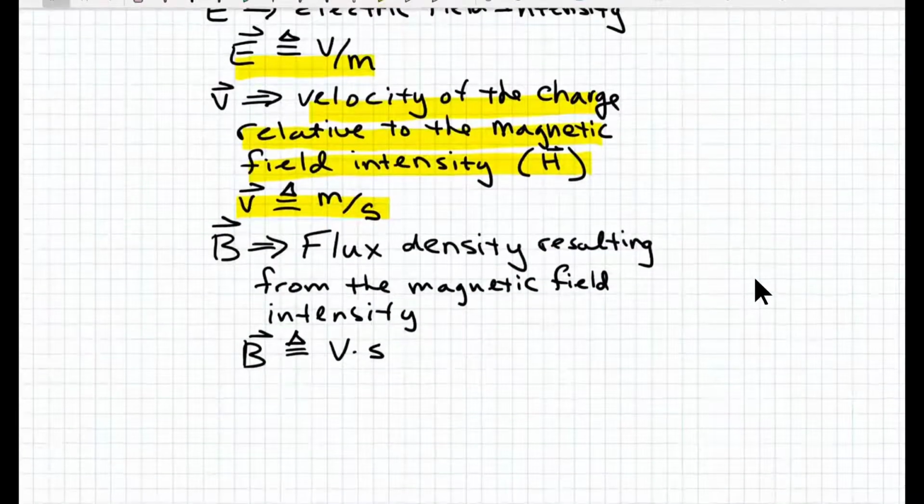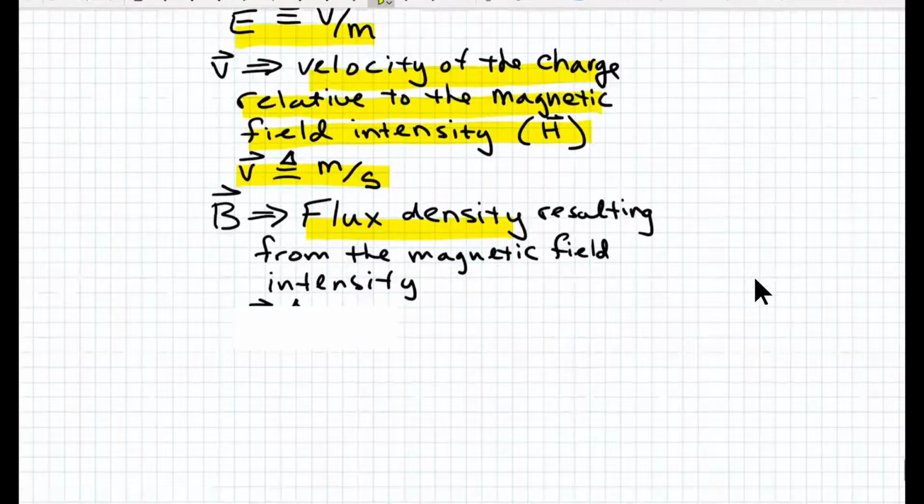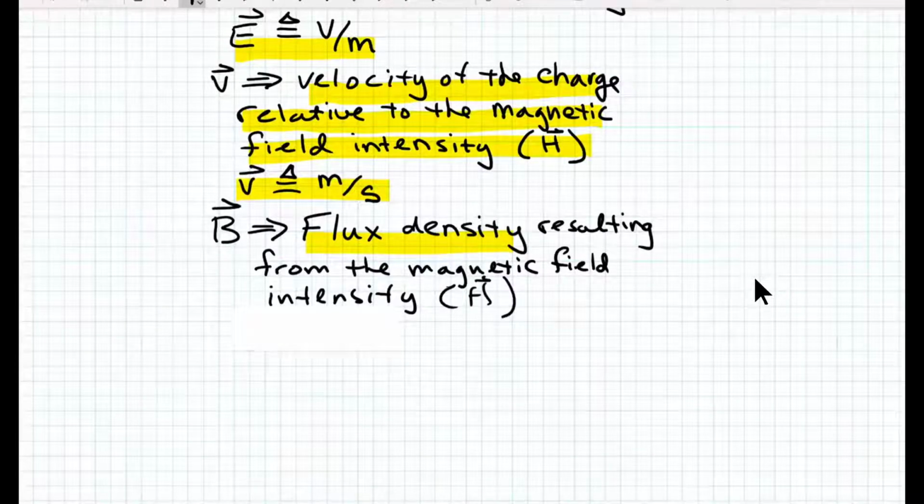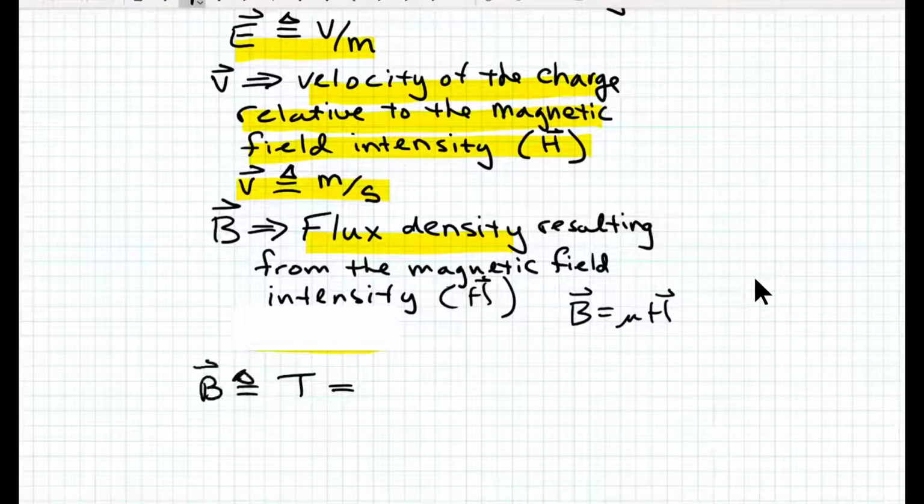We've already introduced flux density, that's the B. It's corresponding to essentially the same H that we were talking about above there. Basically, remember, B is equal to mu H. So if you have a B, you have an H, they're just different by the permeability. And then the Tesla was the unit that we used before, right? And that was the same as Webers per meter squared.